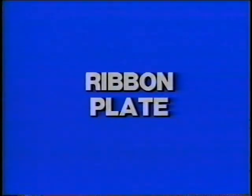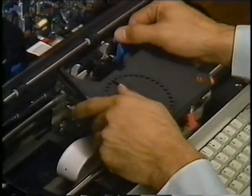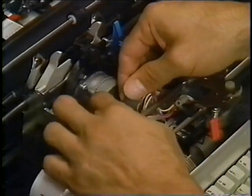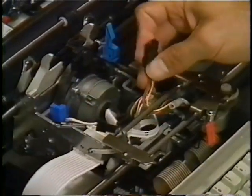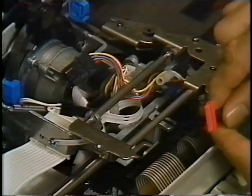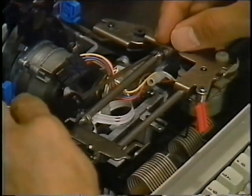Let's see how to remove the ribbon plate. Start by removing the ribbon and correction tape cartridges. Next, disconnect the ribbon feed motor connector. Remove the ribbon plate load spring. And remove this C-clip.